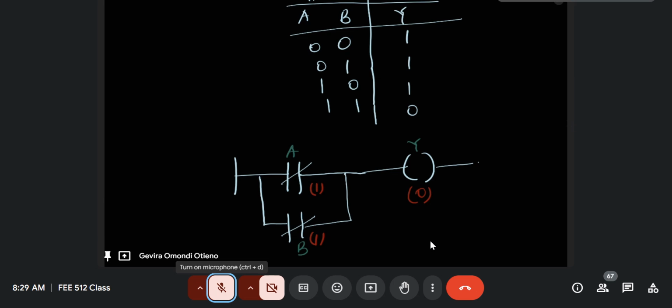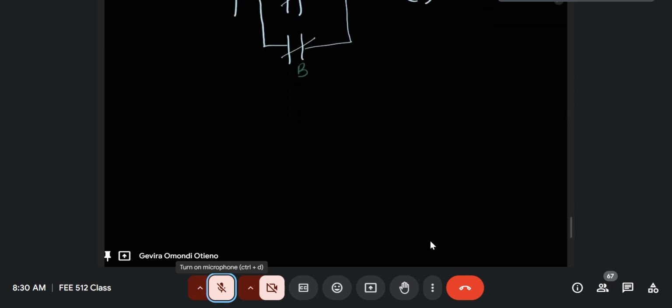So you can see that for a NAND gate, we are now using the OR structure, so you just don't cram. Please understand the concept before you draw the ladder diagram, okay? And you will see that a NOR gate would now be the opposite of what we drew previously. I will not do all of them for you, ladies and gentlemen. I will do the XOR gate because that usually confuses students a bit, and then I move on. I hope that you will read the notes and also do the NOR gate.